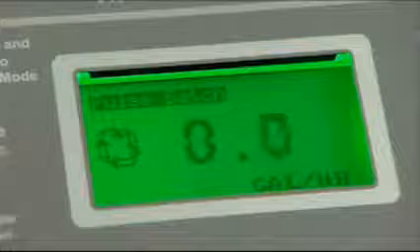Press the front panel Select Run Mode button until the pulse input mode is selected. Press the Start button. When the required number of input pulses is received, the pump will initiate the batch.